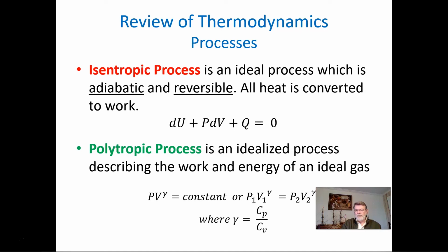So if we know the pressure and the volume at state 1, and we measure the pressure at state 2, as long as we know what gas it is and what that temperature is, we can find out every single parameter of the transformation of the process. So for gamma, we can look up tables, so get that Cp or Cv. We can get the gamma value quite easily. Each gas has its own gamma value on those tables.